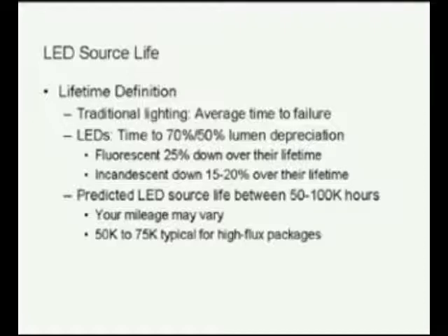Well, the real answer is your mileage may vary. That's not meant to be a glib answer. It really is the case that it depends on the environment. It depends on the engineering of the fixture around the LED. But predicted LED source life is between 50 to 100,000 hours based on maintaining temperatures at prescribed levels. And that's quite typical for high flux or high brightness LEDs.